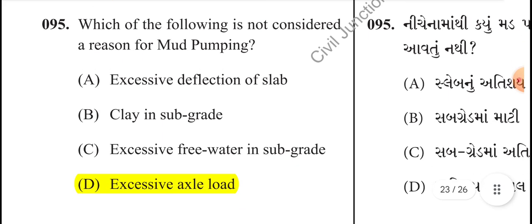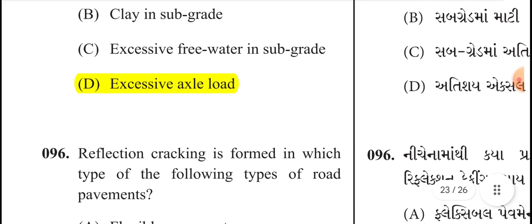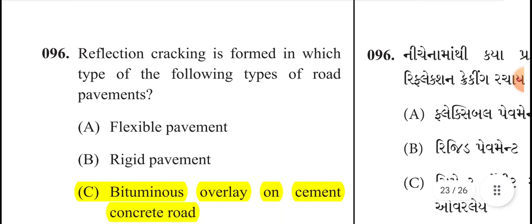Which of the following is not considered a reason for mud pumping? Excessive deflection of slab, clay in subgrade, excessive free water in subgrade, excessive axle load. For mud pumping, the answer is excessive axle load.